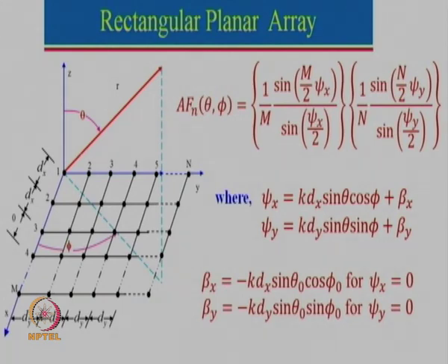You know that for a linear array, a beam width relationship is there with the total length. From that you can find out the total length, and then you can see the number of elements required. As a starting point, you can take d as lambda by 2, but you can always adjust that. Instead of 0.5 lambda, you can take 0.6 lambda or 0.7 lambda or maybe 0.45 lambda, but not more than 0.7 or 0.8. Now you might wonder, if I take more than 0.7,